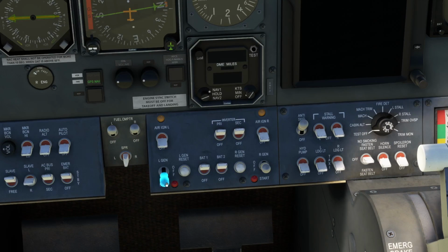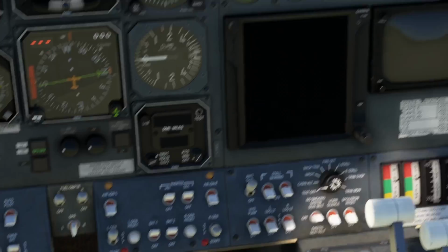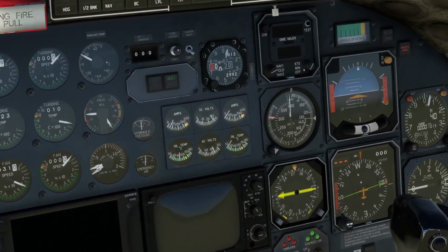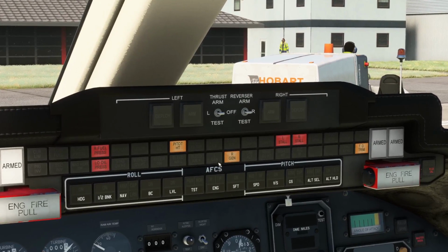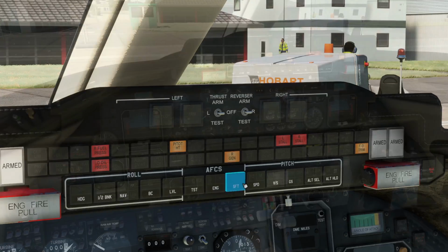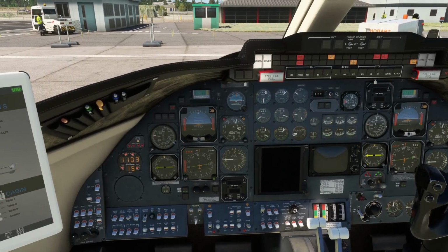So we've got engine number 1 started. I'll take that switch out to start position and put it into left generator, and we come back up here, and now we can see that on the left we've got a load of about 50 amps showing, and our DC volts have now gone up to 28, which shows you that the DC system is being provided by the generator, and our left generator caution light has extinguished. Exactly the same for the right engine and the right generator.